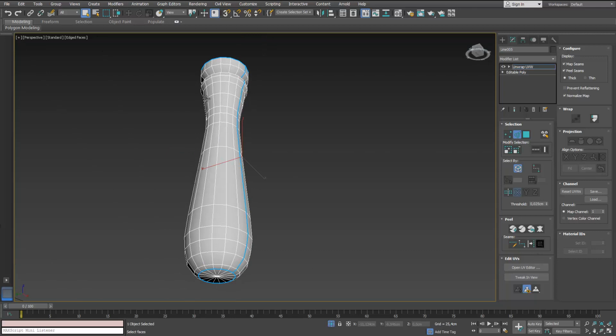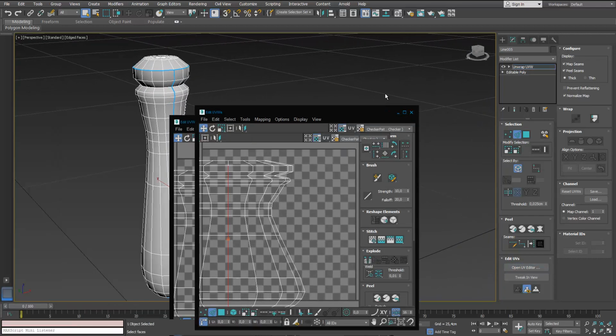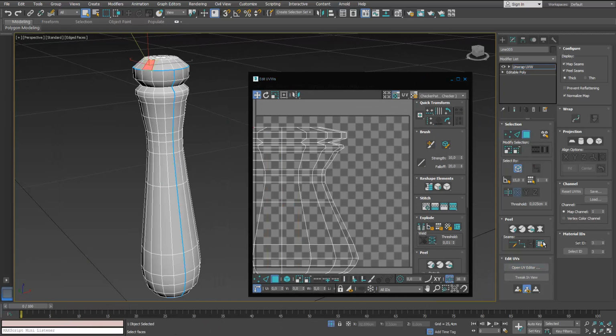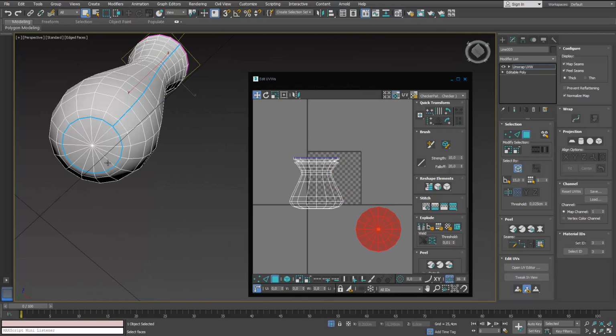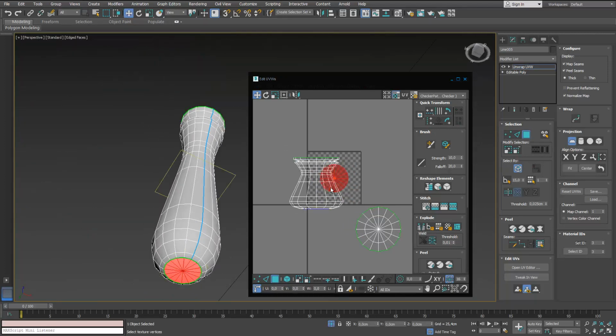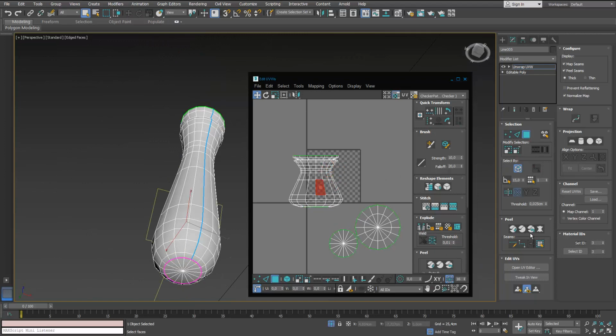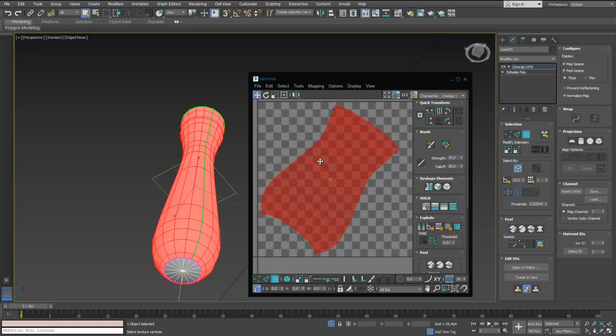Keep holding Alt actually to deselect the areas that you don't want, and you're gonna end up with something like this. And we're gonna apply the pelt method, as you will see, on the piece that is the biggest, and the planar pieces from the top and from the bottom are gonna be similar. So we're gonna make them flat and planar.